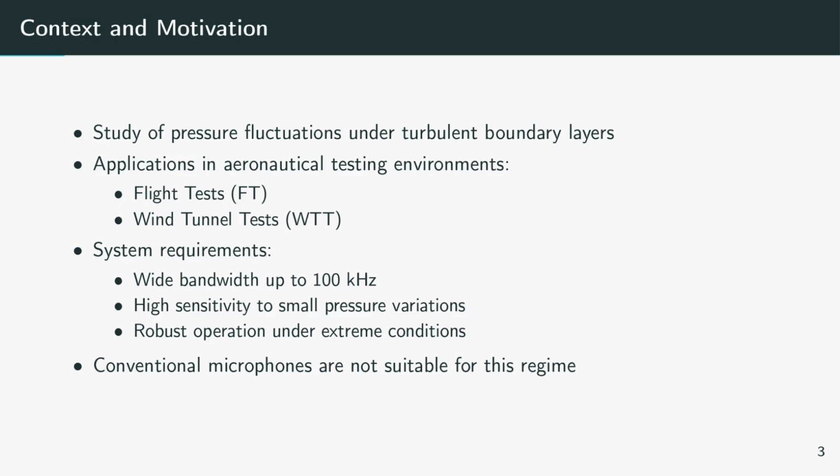The system must satisfy several strict requirements. First, it must operate over a wide bandwidth up to 100 kHz in order to capture both low-frequency flow structure and high-frequency turbulent components. Second, it must provide high sensitivity since the pressure variations can be very small. Finally, it must remain robust under extreme environmental conditions, typically found in aeronautical testing.